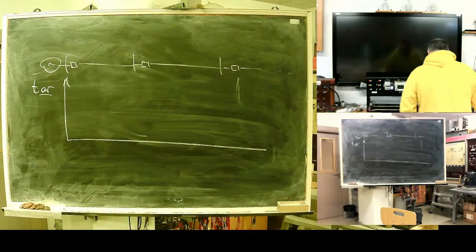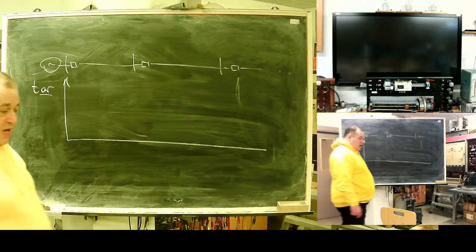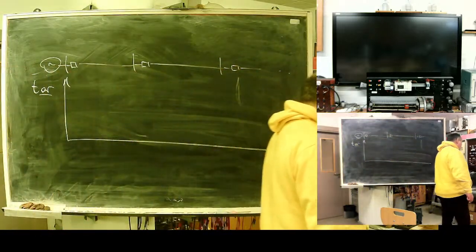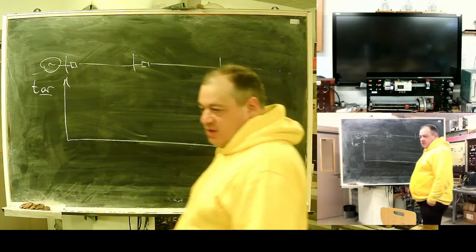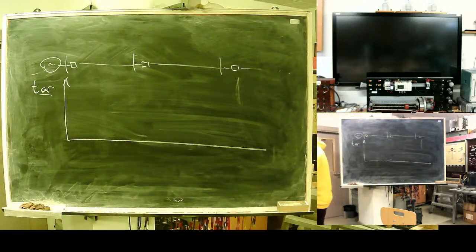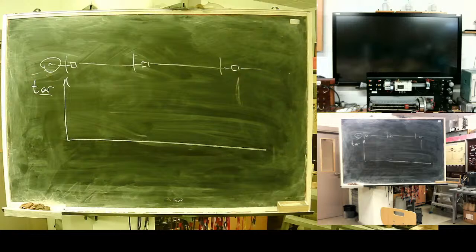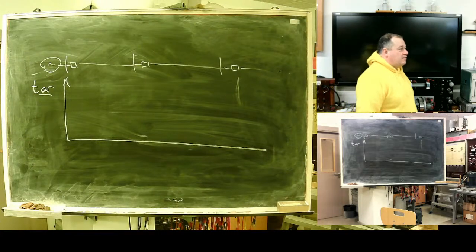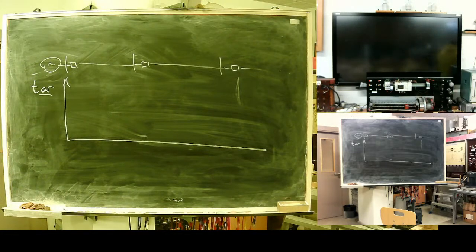One more thing. Many network operators prefer installation of minimal voltage protection. First, it prevents stability disruption called voltage avalanche. When you have a really serious penetration of industrial load, there can be a situation where you have a deficit of reactive power, and if asynchronous machines are put under voltage conditions, they start to consume reactive power aggressively.